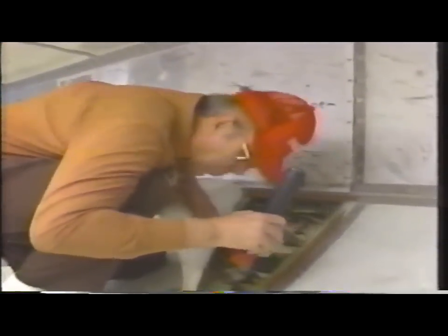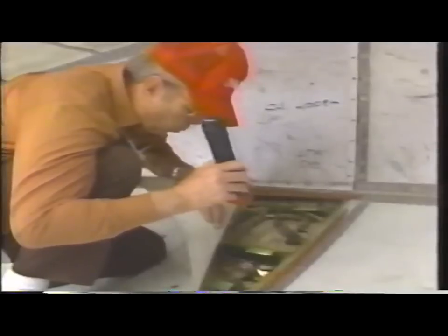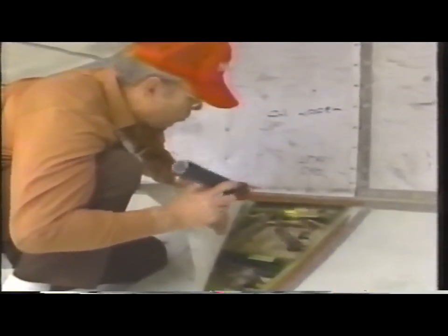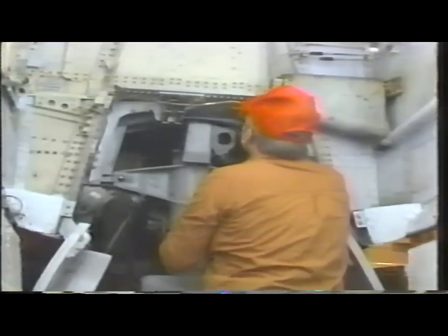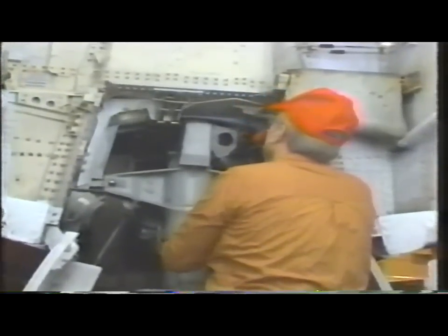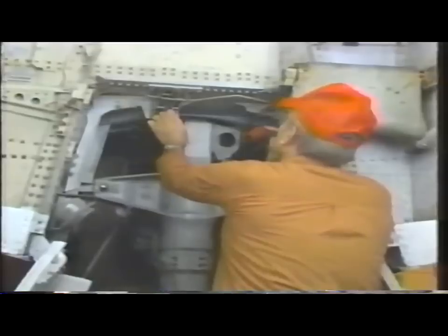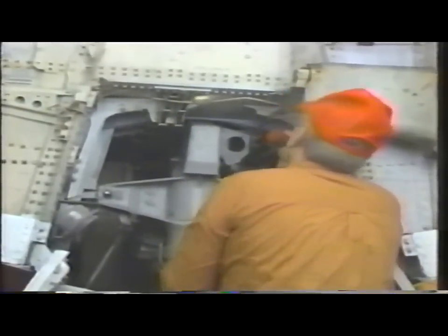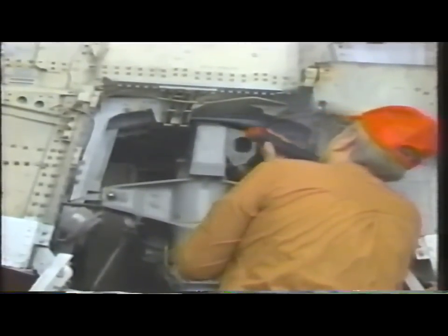Pay particular attention to the paint coatings and make sure they are still intact. You should also examine areas where heavy grease coatings are used as preservatives. If the coating is in question, remove it and inspect the area underneath.